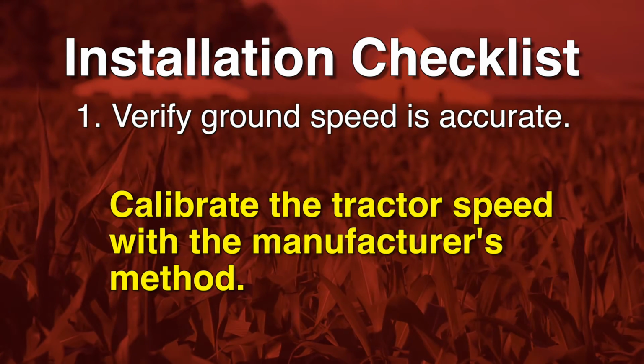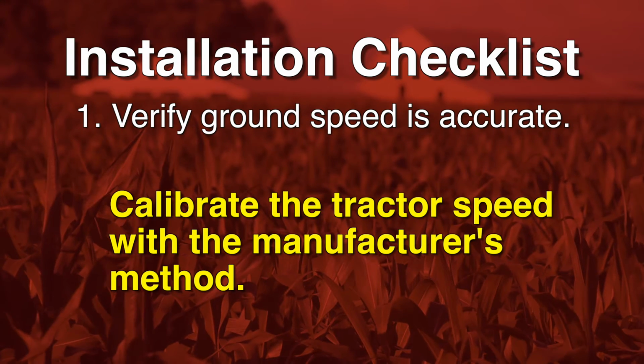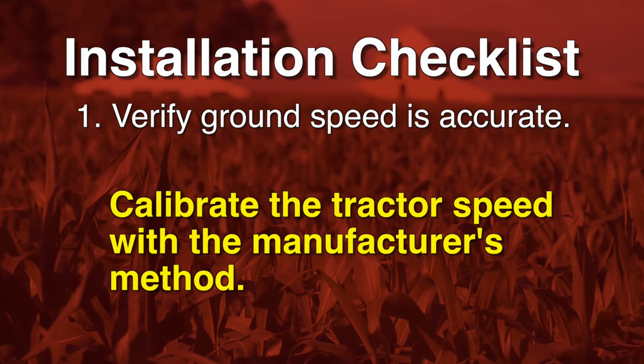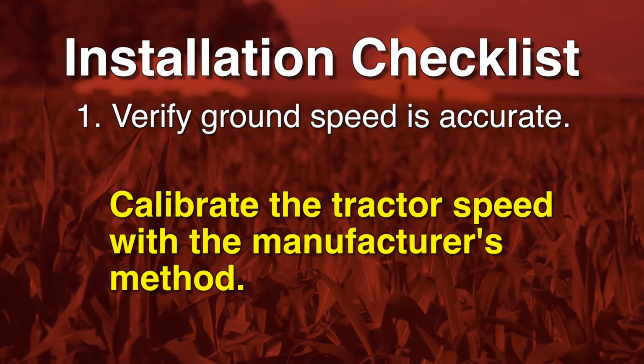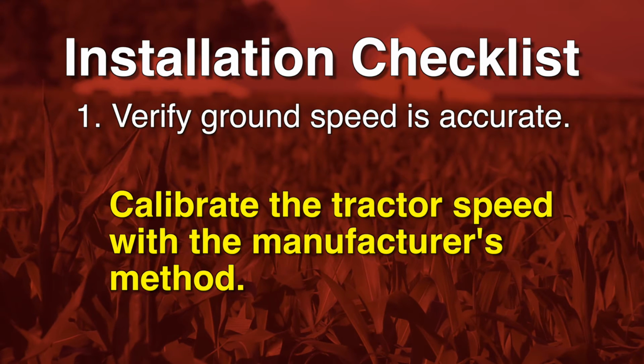If the tractor speed is not correctly calibrated, you may see a discrepancy between the A-post speedometer speed and the ISOBUS display speed. Because the ISOBUS is getting its speed from a GPS source, it is most often accurate. The solution is to use the manufacturer's method to calibrate your vehicle's speed.